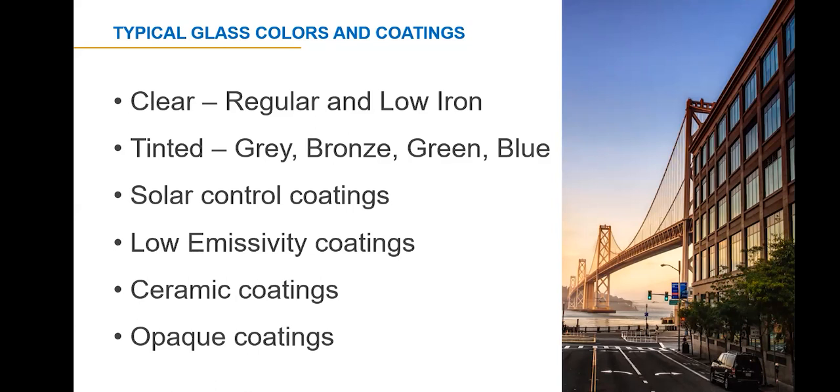A sputter coating is applied offline in special equipment. This process deposits the metal particles onto the glass in a vacuum chamber. Almost any non-magnetic alloy can be sputtered, the more common being stainless steel, silver, and titanium. Performance characteristics and color depend on the alloy and the coating density. In general, they have better solar control performance than pyrolytic coated glass.